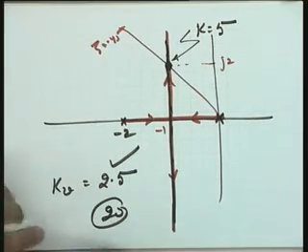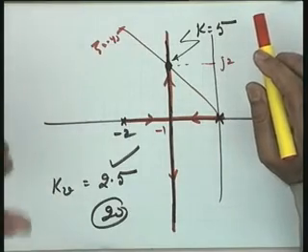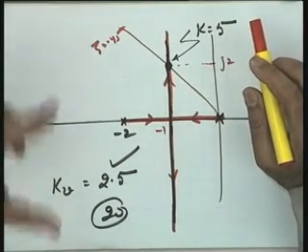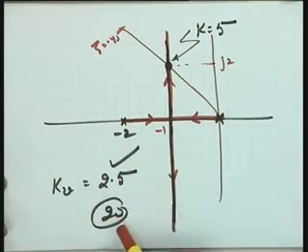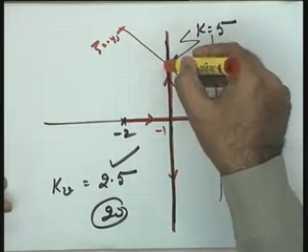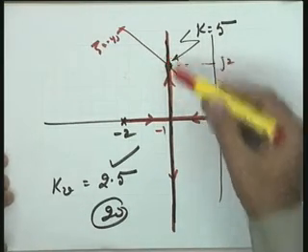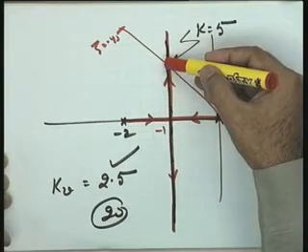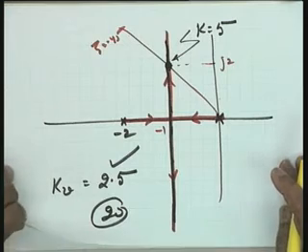So what will you do? I want to add the compensator pole and zero to satisfy the twin requirements. One, the Kv should be boosted from 2.5 to 20, and second, the compensated root locus plot should also pass through this point. These are my requirements. The third, of course, will be the dominance condition, which anyhow you will have to see. If the compensated root locus plot passes through this point and the Kv is boosted to 20, the requirement is satisfied.